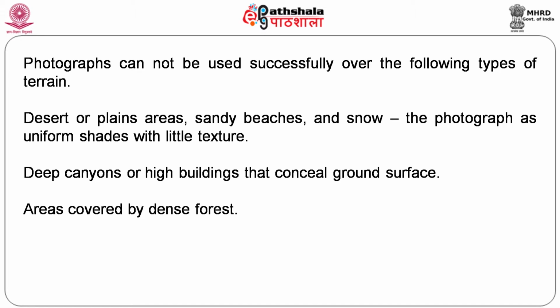Of course, obviously then you talk about your dense forest. In a dense forest you cannot use satellite images directly. Aerial photographs can be used because you have the advantage of going lower and lower. I told you 1 kilometer, 1.5 kilometers, 2 kilometers, that will be the altitude at which you will be flying. So, you will be in a position to look much closer to the forest area and then use it.